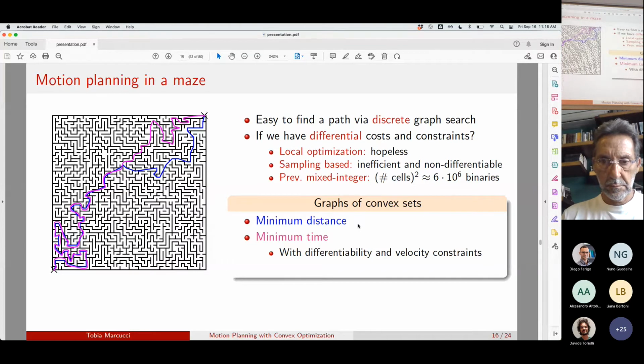And there is a geometrical reason, because the way they were writing the problem down before was not ideal, actually wrong. They were still using binary variables, but they would associate the footstep to a region with a fixed horizon in front of you. If you take the natural convex relaxation of something like this, it says to move anywhere in the convex hull of the stepping stones you have in front.